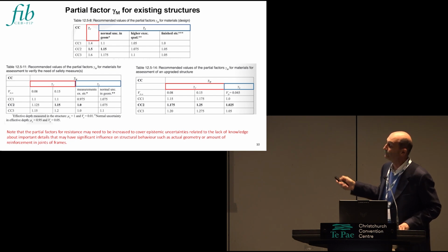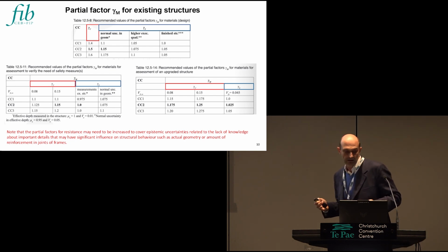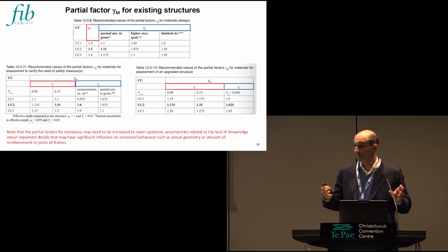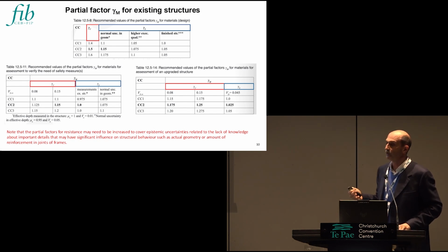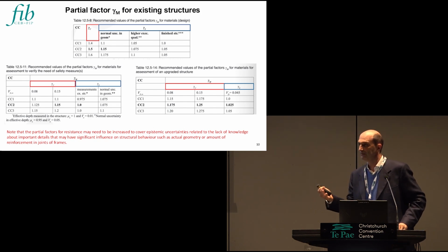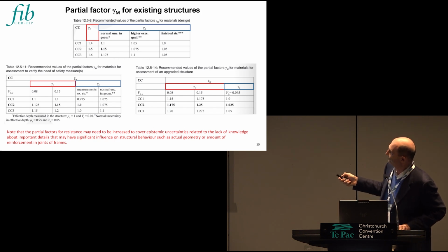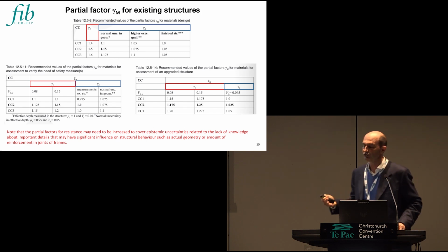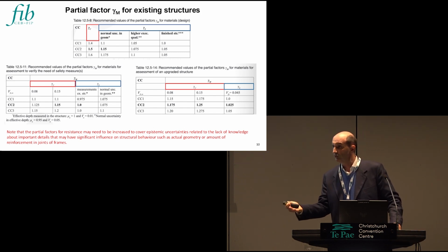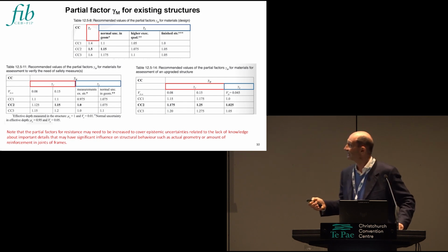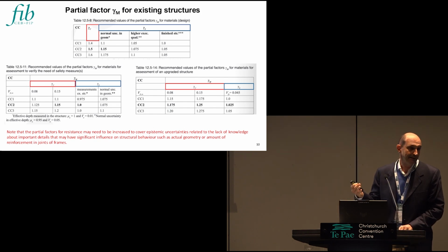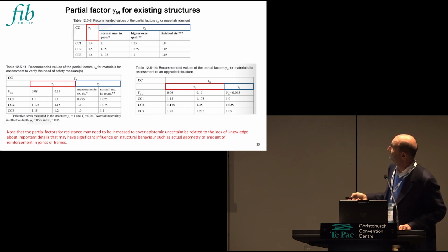And still, for example, you know that when we define the gammas for the steel, we have several uncertainties inside, particularly for the position of the reinforcement, the detail of the reinforcement. And it's clear that this is for new structure. We can have different gammas related to the knowledge that we have, the quality control that we have, and so the different dispersion and detailing of our structure, mainly the actual depth of the beam.